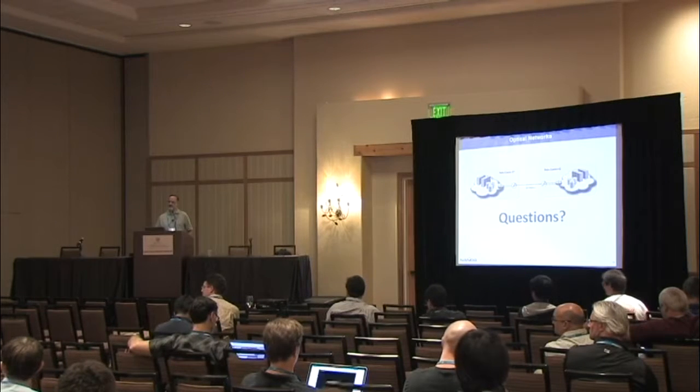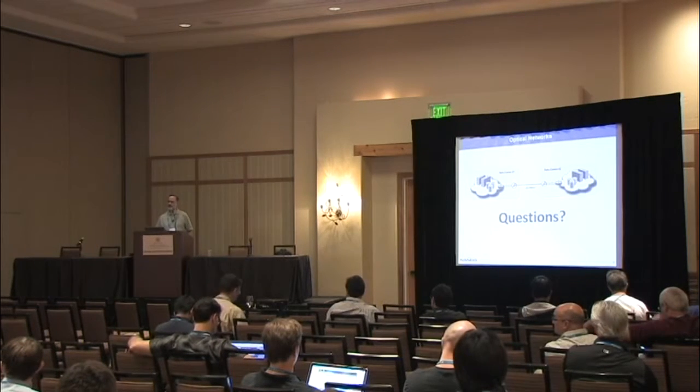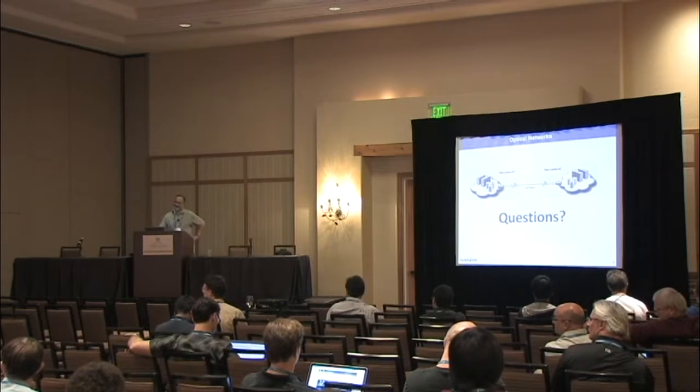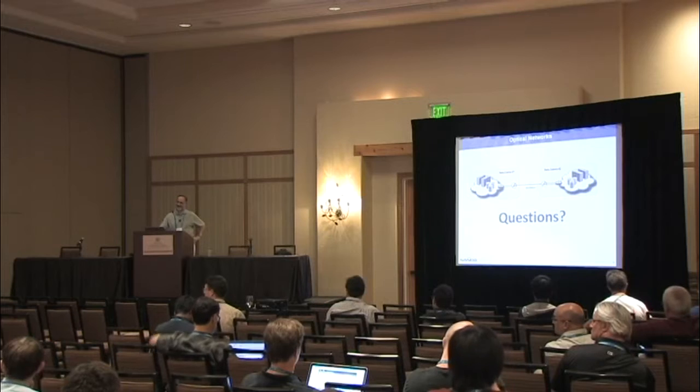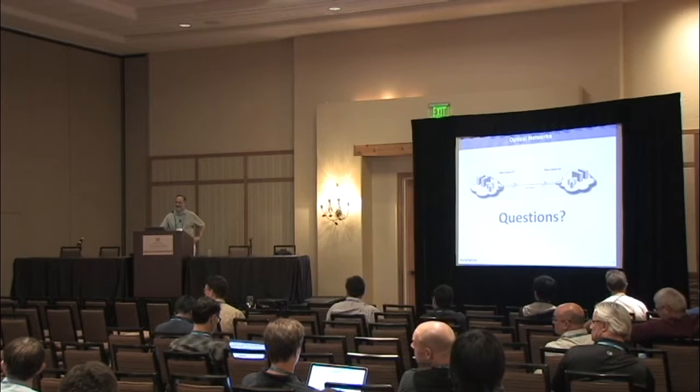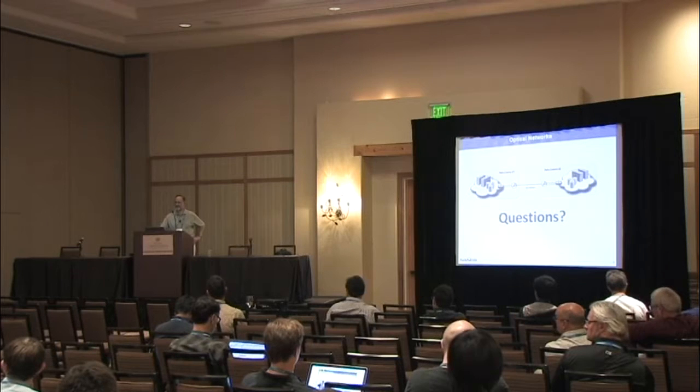I know it's not exactly in the presentation, but I would like to hear something about what yourself and other vendors are doing on the path forward to 400 gig and terabit. And I'd also kind of like to speculate a little bit beyond that. So we're starting to approach some pretty significant practical physical limitations within the fiber. There's only so much bandwidth you can stick on a single mode fiber before the wavelengths get short enough that the single mode starts to behave like multimode. So I'm just kind of curious, what is the far reach of the industry at this point?